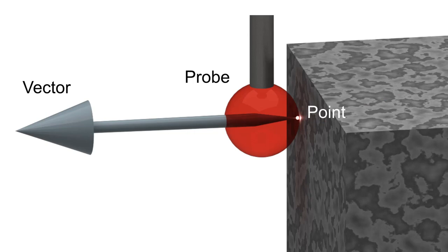All right, so this is the general arrangement. You have a probe, and the probe, at least most probes, just have an on-off sensor, essentially, that tells the CMM that this has touched something. Now, you could walk up to this probe and touch it, say, down here, and all it would know was that it touched something. It would not know that you touched it over here in this location.